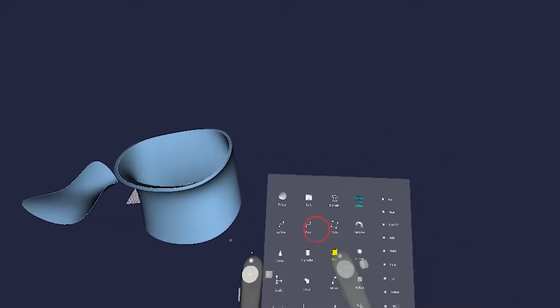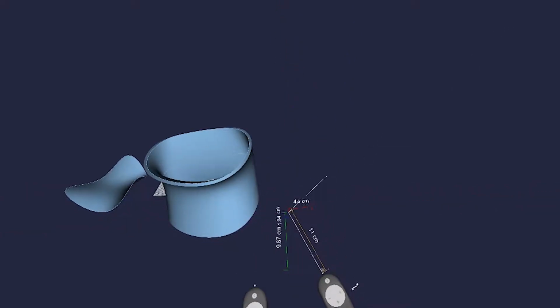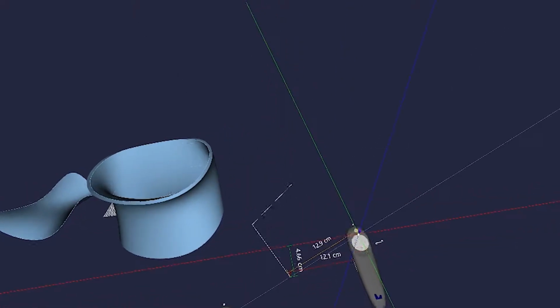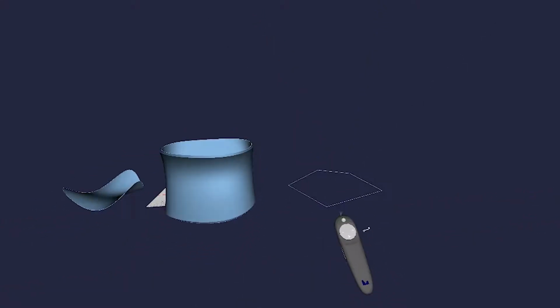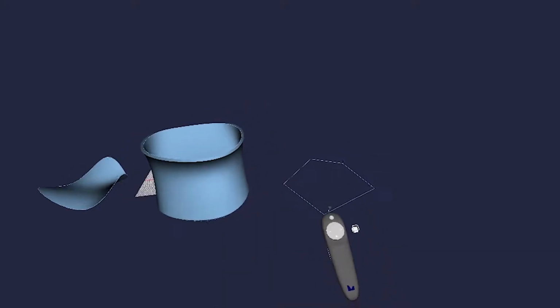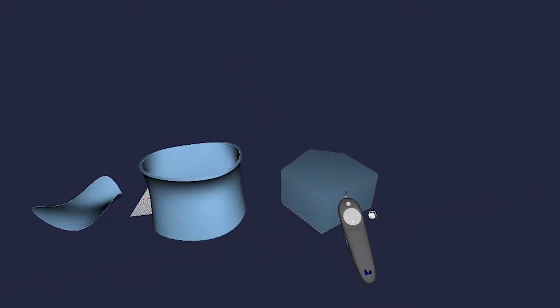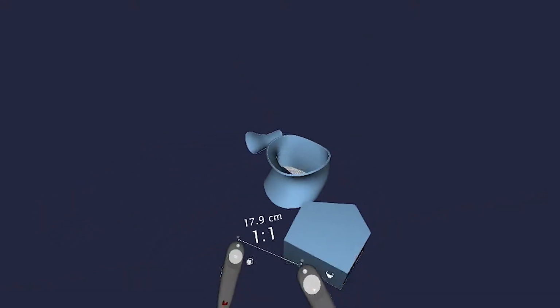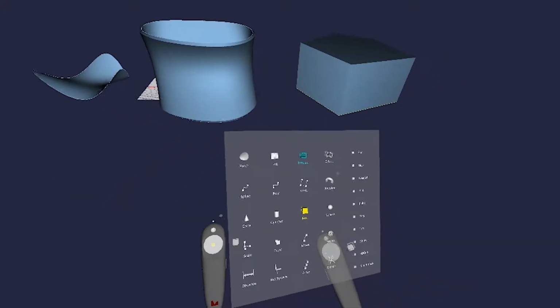So next we're going to make a polygon using the poly tool, which we're going to do our last command, which will be to extrude a curve, in this case a pentagon. So open up the tool palette, and at the top you'll see extrude, select the curve, and bring it up in the Z direction. If the closed curve is flat, it will create a solid extrusion.